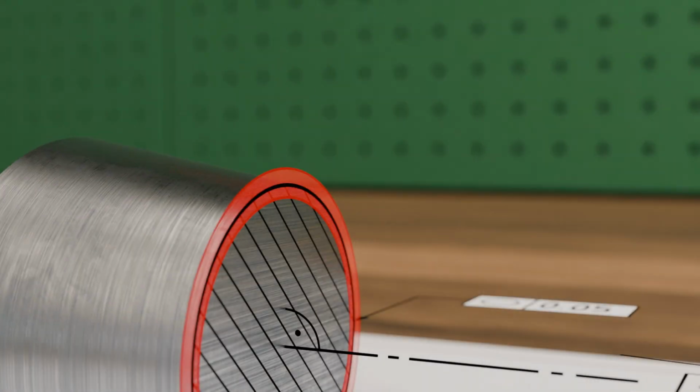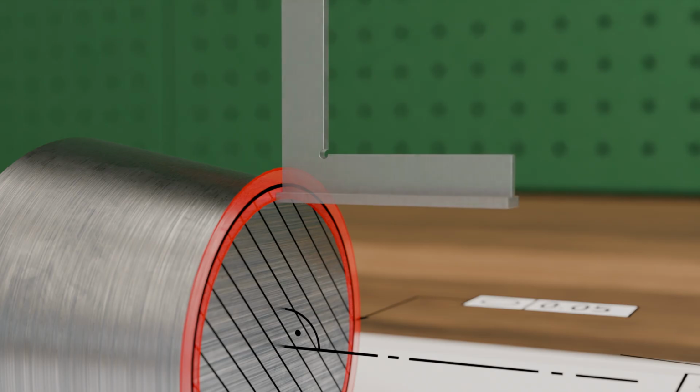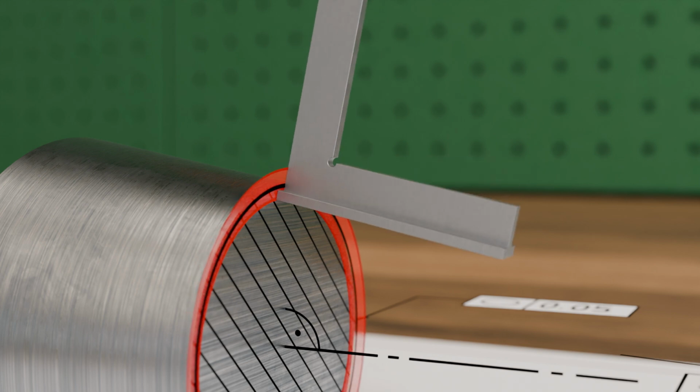Basically, for non-cylindrical surfaces, there are two possible ways the tolerance zone can be oriented. In the case shown, it lies directly in the section plane and is therefore perpendicular to the centerline, that is, perpendicular to the part's axis. However, this does not necessarily have to be the case, since the tolerance zone can also be oriented perpendicular to the part surface, meaning perpendicular to the conical generatrix. In this case, the ring-shaped tolerance zone forms a conical surface, with a distance between the concentric circles defining the conical surface still corresponding to the specified tolerance value of 0.05 mm in our example.